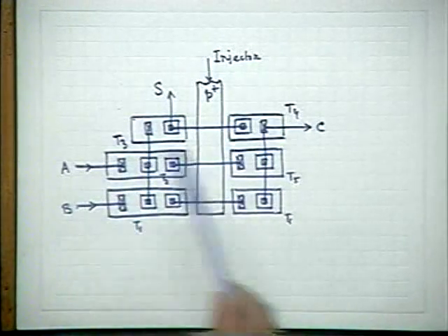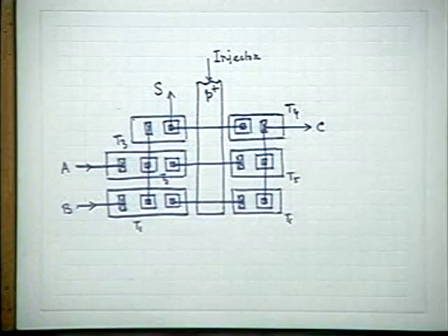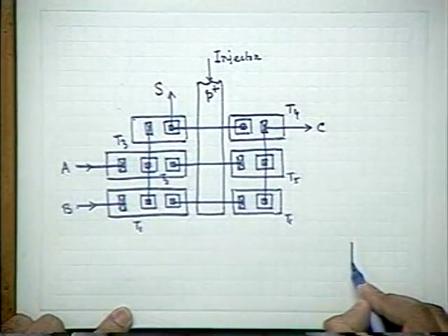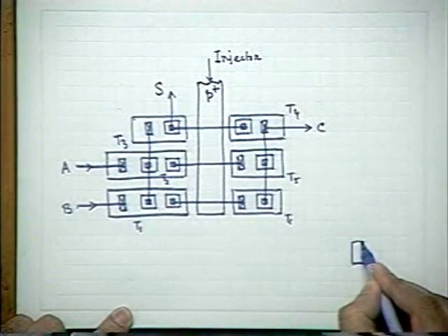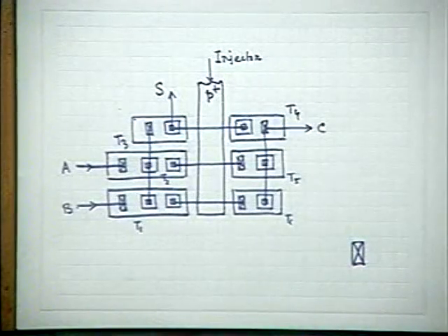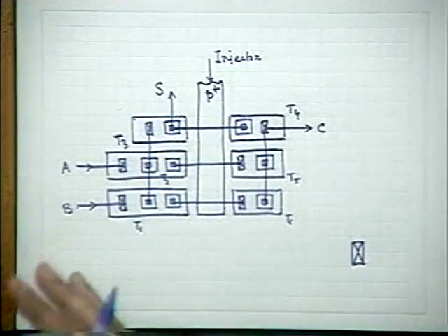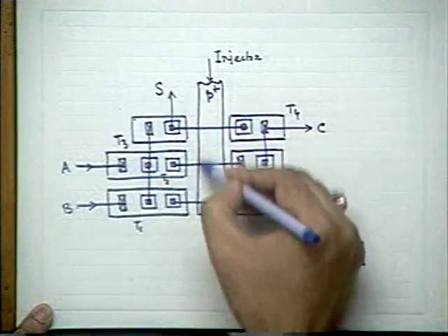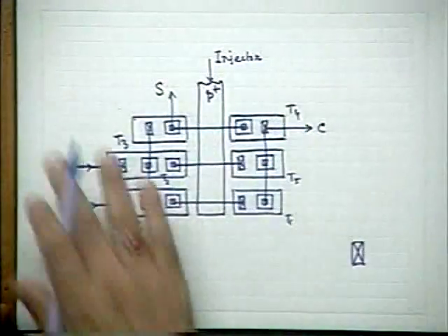You see that, however, I think you know that whenever I draw a box and put a cross here, that's the convention, it indicates what is it? Contact holes. This indicates the contact holes which are used for making the contacts with the different emitter, base, collector, etc. So this is the base contact hole. This is P+ injector in an N+ epitaxial film.